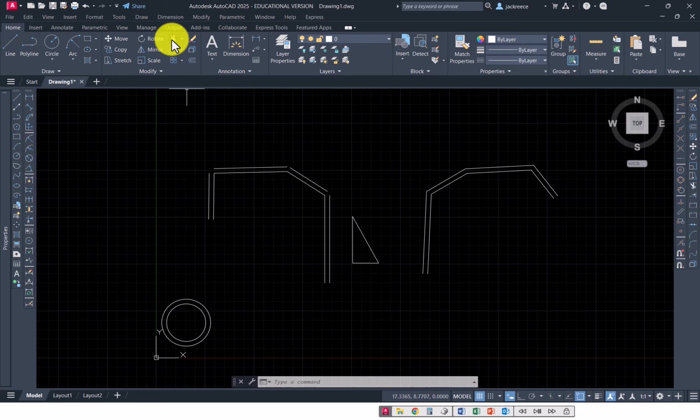And up here, you got the scissors for trim, and then you have to pull down, you can change to extend. Okay. So let's start with the extend, okay? And the keyboard is like EX. And so what we do is we extend, it has to extend to something that would cross it normally. So you see, I can't extend any of these. I could extend that one over to there because it will extend over to that line.